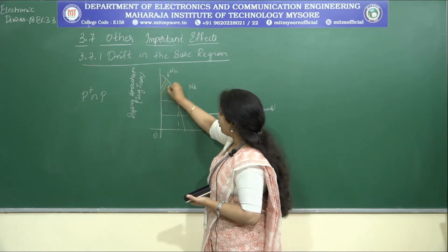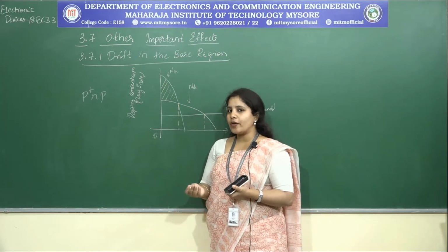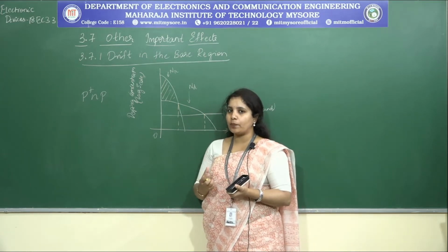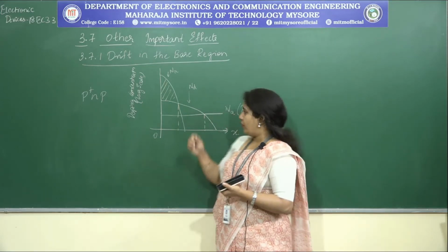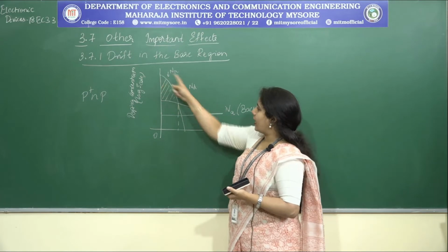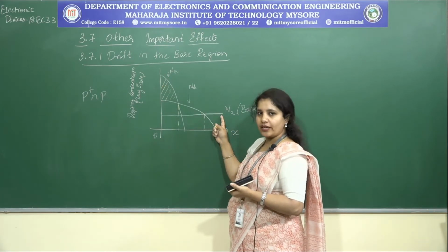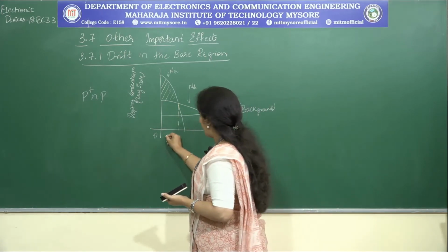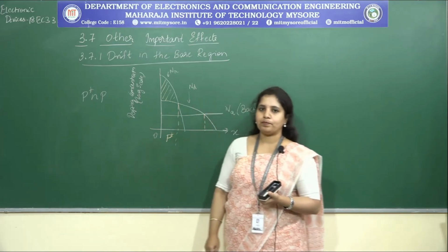It is the acceptor doping that is dominating, right? So if the acceptor doping is dominating, then which kind of material am I obtaining? It is a p-type material. Now is this acceptor value very much greater than the initial acceptor doping that I have done? Yes, that means this region is nothing but your P plus region.